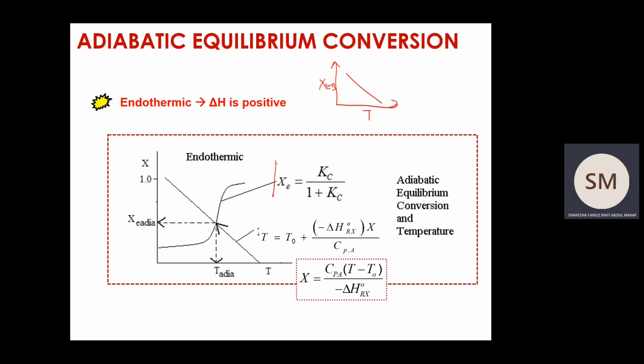Okay, X_E is this one, and the straight line with a negative slope is actually referring to the energy balance here, X_EB. So this one has no plus delta C_P term, because delta C_P is equal to 0, because only one pure compound enters.